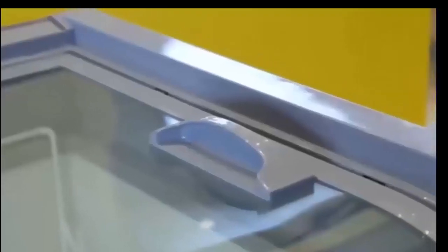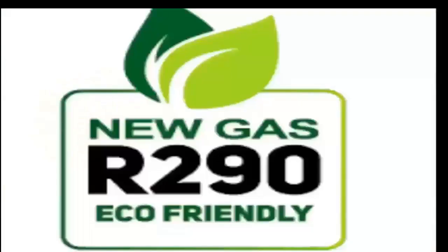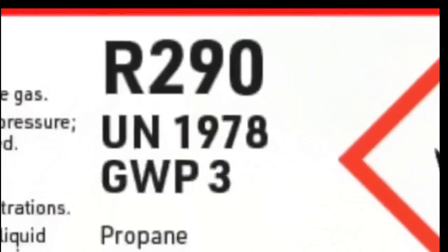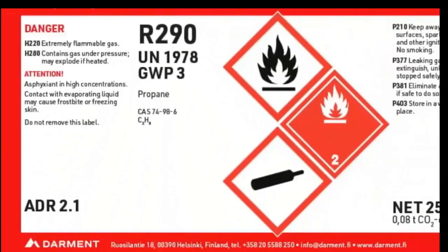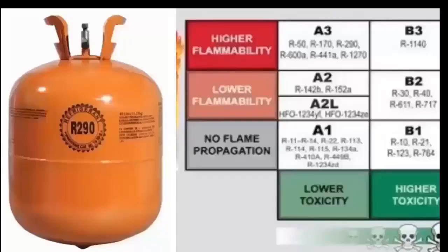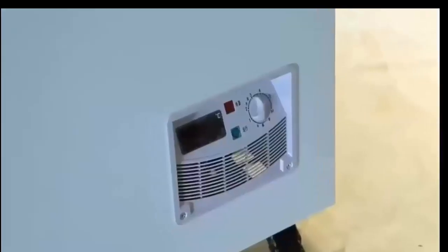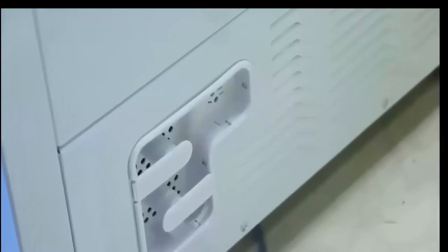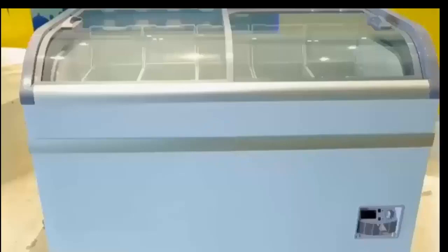The main advantage of R290 is that it is not affected by environmental restrictions because it does not affect the ozone layer and it has a global warming potential GWP of only 3. Therefore the availability of this gas is guaranteed for many years, which is important above all when considering the investment in various equipment. The main disadvantage of R290 is its flammability, classified as A3. But since R290 is used in equipment of medium and lower capacity, this danger is low because the equipment does not have enough refrigerant to be a considerable danger.